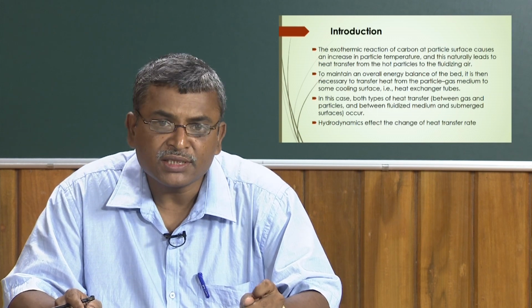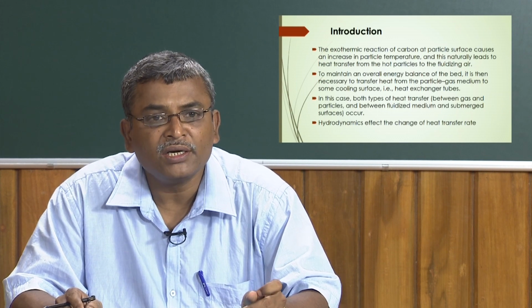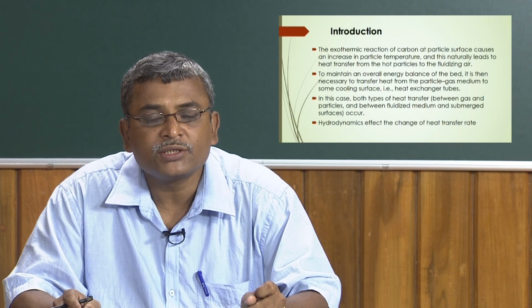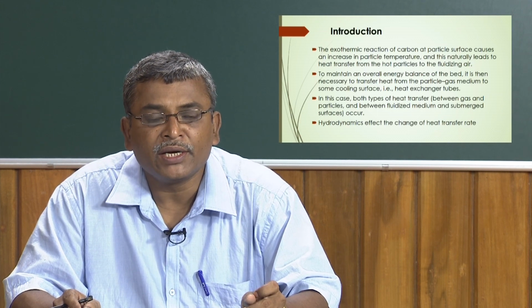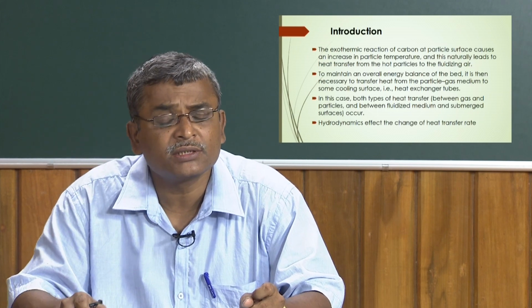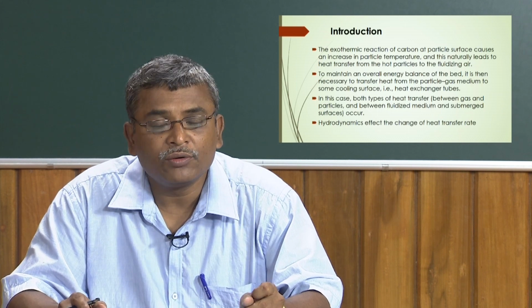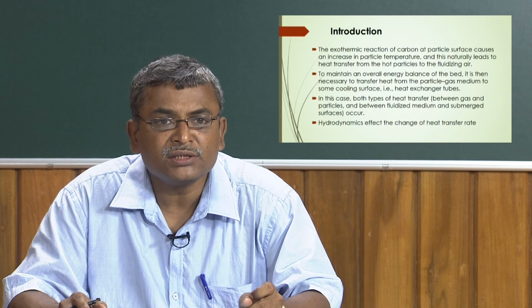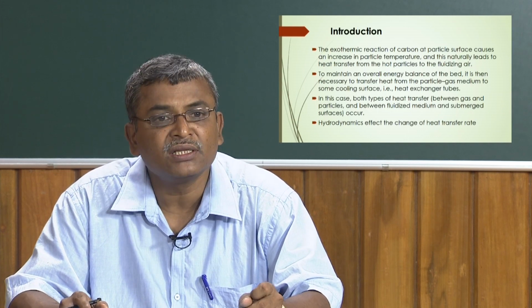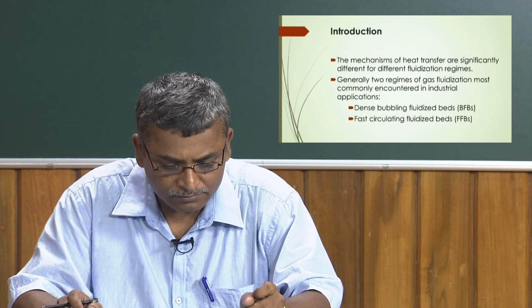And very interesting, whatever hydrodynamic characteristics we have learned earlier, like flow pattern, hold up characteristics and the entrainment characteristics, even the mixing characteristics of the solid particles, segregation and elutriation, all those hydrodynamics will be affecting the heat transfer rate inside the fluidized bed.